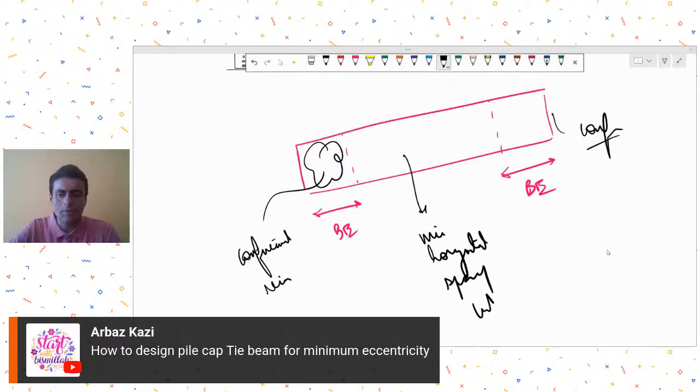Have your pile points on spring supports, and have the column loads assigned, and then connect it with tie beams. So automatically you will see the appropriate moments getting transferred to tie beams, and then you can design that tie beam for it. Okay,